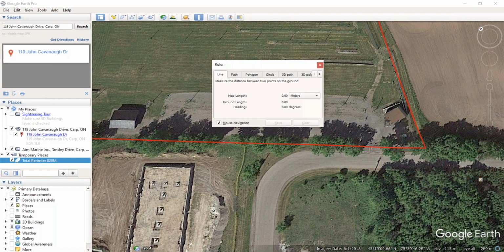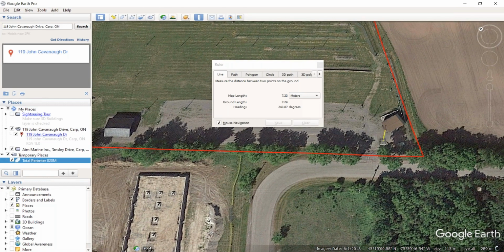And I want to mount my very first processor as close to my sliding gate as possible. One of the reasons we want to keep in mind where we locate equipment is, again, for communication aspects, trenching, and how little we can affect the critical infrastructure at the site. As everybody knows, equipment is not always the total driver in a project. It's labor, and especially with a traditional fence line sensor, civil cost can be great. So if I draw a line from here to here, I know that I have 16 meters. Fantastic. I'm well within any form of communication that we could use.